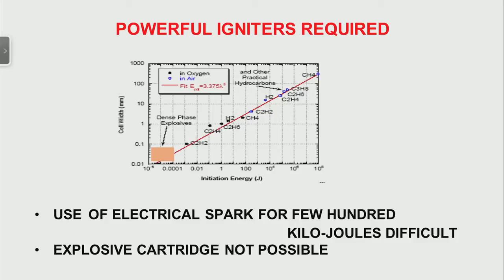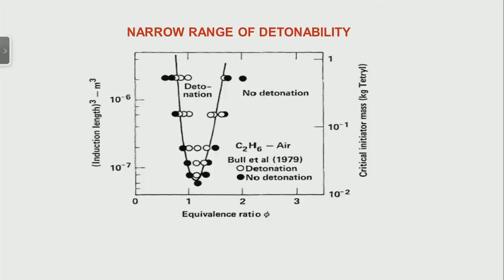Well, this tells us the way in which a detonation gets initiated, and about the 3-dimensional structure of a detonation wave, namely a characteristic fish scale or diamond structure, the characteristic size being the cell width, which is a very important parameter for a detonation. Having said that, let us go back and see whether, like flammability limits, there is a range of mixtures within which only a detonation can propagate.